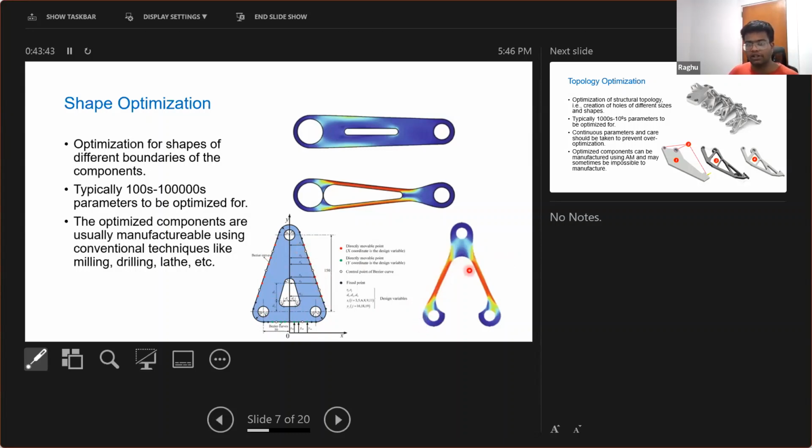If you see, you get this bracket, and visibly it is much lighter in weight, but though it looks flimsy, it is based on the numbers, based on the constraints you are providing to the optimizer. Say you are not using this bracket in a high stake situation. Say you know that there are not going to be too many stresses on this bracket. So it doesn't need all that material. It can shed off all that material and it is just this.